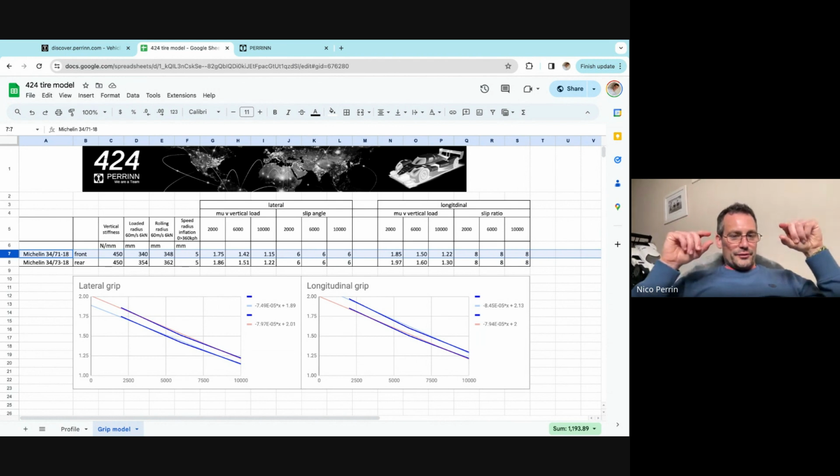That split is fairly small on 4x4, again, because it's a four-wheel drive car. We've tried to look at it: the rear tire is more or less as good as it can get. We will not get a tire that's got more grip than that. But for the front tire, we've got a choice. We could put the same tire as the rear. We've tried and it doesn't work. We could also put a smaller tire and drop the grip at the front. So what we found with 4x4 is we want less grip at the front, but not too much. Just a 6% difference is really good.